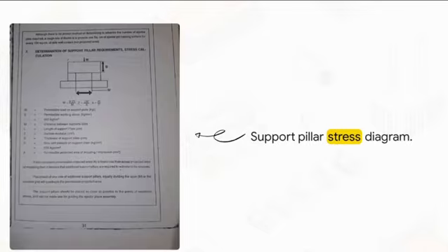Picture this. When you inject molten plastic at ultra-high pressures, the mold literally wants to bend and bow. We use support pillars to stop that from happening. Notice the 3 interconnected equations here for W, Z, and A. They calculate the permissible load, the section modulus of the plate, and the permissible projected area. At a glance, they might look separate, but they're actually a single connected chain of logic.